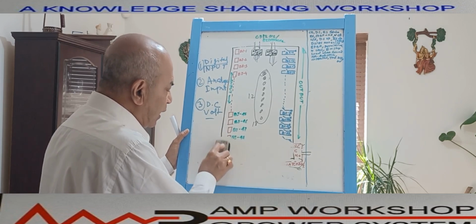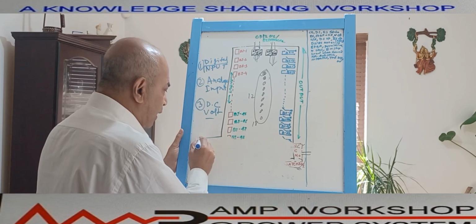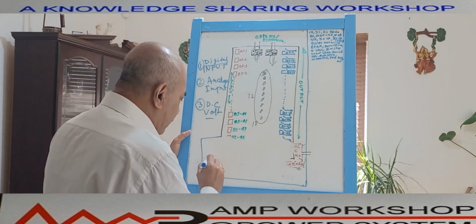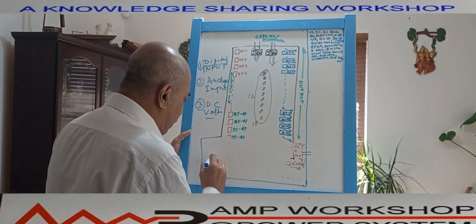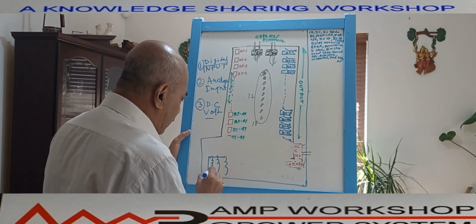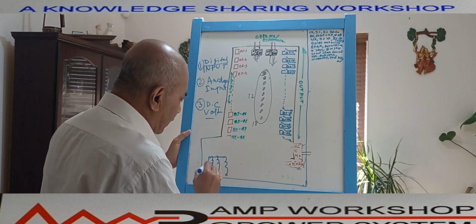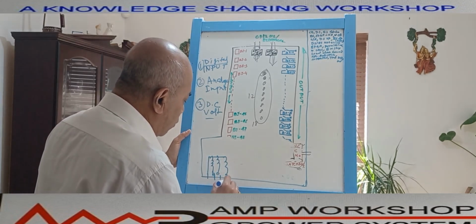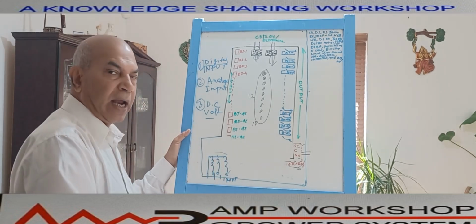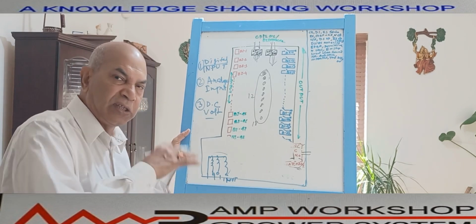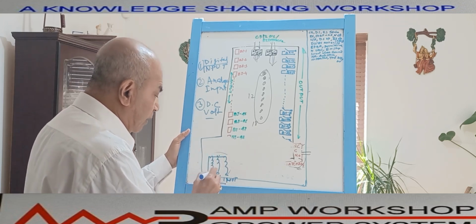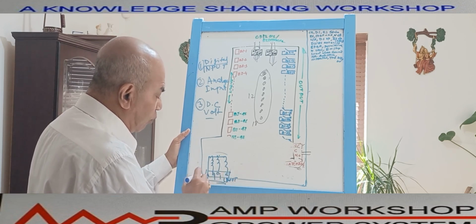If you see the digital relay at the base, you can see there are analog input termination features available. There is a terminal. Suppose there is a VT terminal with 4 windings, suppose this is a VT, and then it is neutral. You can see this is inside the VT. Suppose you are giving 120 volt or 110 volt VT supply here. Internally, it cannot take this 110 volt, so inside there is a winding arrangement which reduces the input voltage to the required level. So these terminals are the input voltage, the analog input we are giving to the relay.